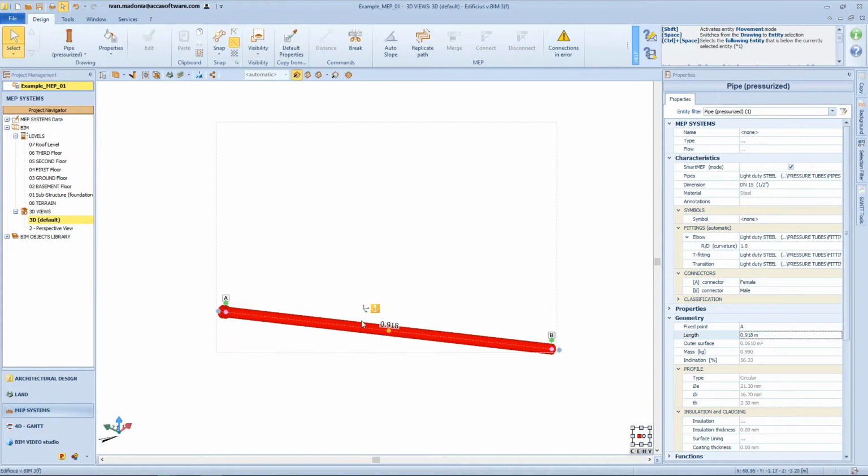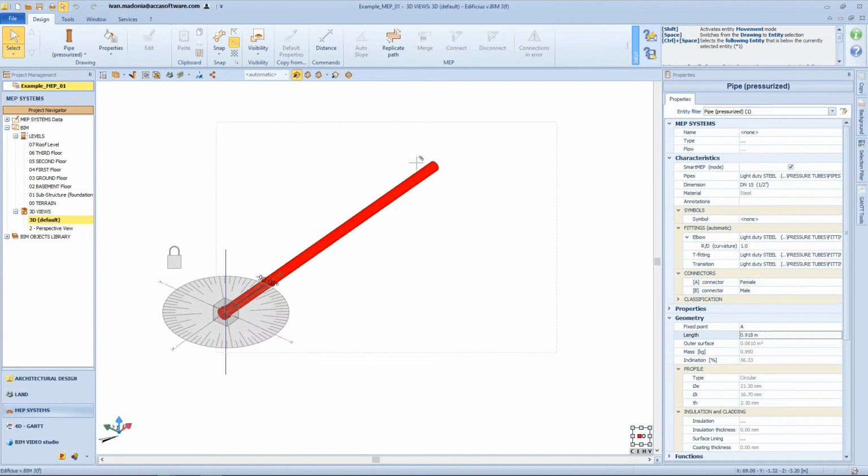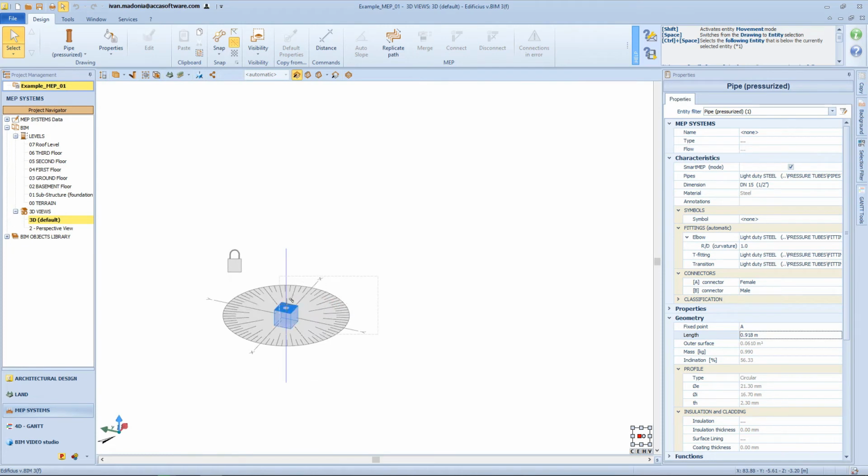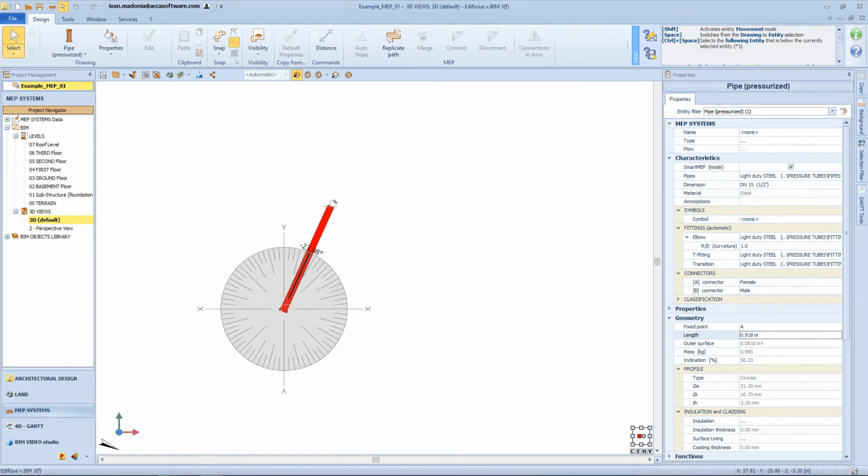The pink circle allows you to reshape the pipe, leaving the opposite end to the selected one as a fixed point. When you click on this circle, the directional cube is reactivated and the initial condition of the tube being inserted is restored. From here you can trace the pipeline in a different direction and/or plane.